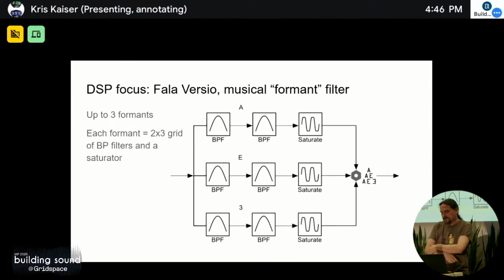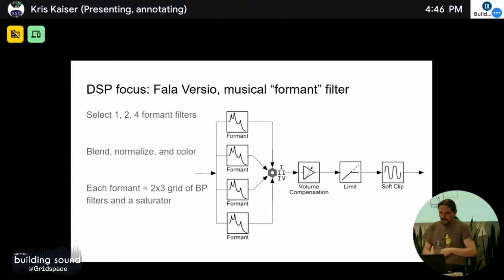So we take that sort of formula, 3 formants, break it down. We build a similar structure, 3 bandpass filters. Those are individually run through saturators because nonlinearities are awesome, I guess. Then on the diagram there, the little switch just indicates you can, on the front panel, control which of the 3 formants you want to use. Very straightforward.